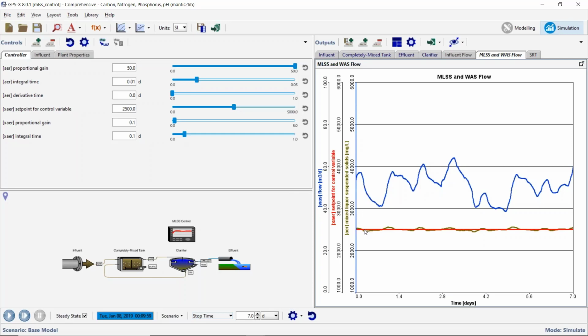And in this case, I would say that I tuned this so that it was pretty tight and it sticks exactly around the set point. It is possible to do it by just turning up the gain and turning down the integral time a little bit. We could get this so that you practically can't even see the mixed liquor concentration underneath here. It'll actually fit it almost exactly. But that means, of course, it's doing much more changes in order to try and keep up with the dynamics of the model, in which case this becomes really quite exaggerated and probably not very realistic at some point.